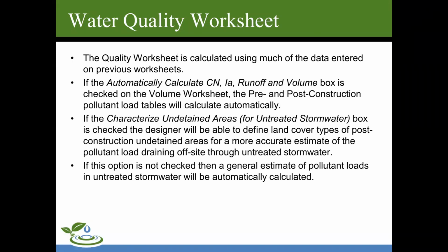The water quality worksheet is calculated using much of the data entered on previous worksheets. If the automatically calculate CN, IA, runoff, and volume box is checked on the volume worksheet, the pre- and post-construction pollutant load tables will calculate automatically.